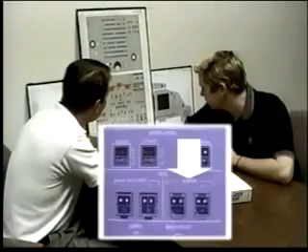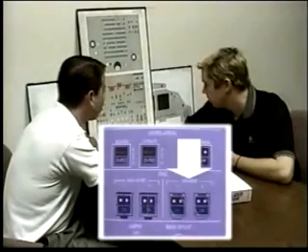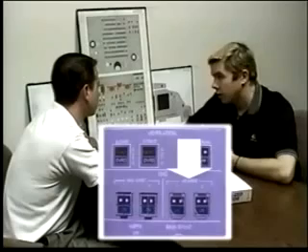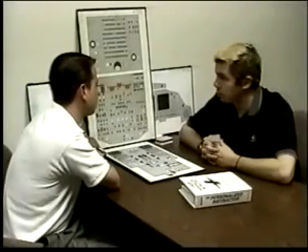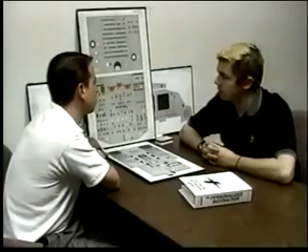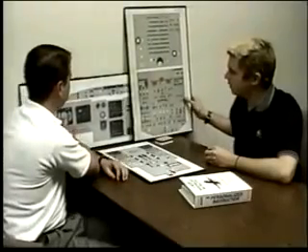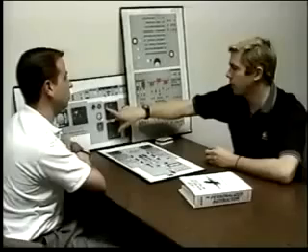On the engines, N1 mode. When might you select N1 mode, and what's our procedure? Well, the IAE V2500 is an EPR-rated engine, so we run around in EPR-rated mode all the time. It's possible for us to fall out of EPR mode if the FADEC has a problem. So what we would see is more than likely one engine would go into an N1 mode, either rated or unrated.